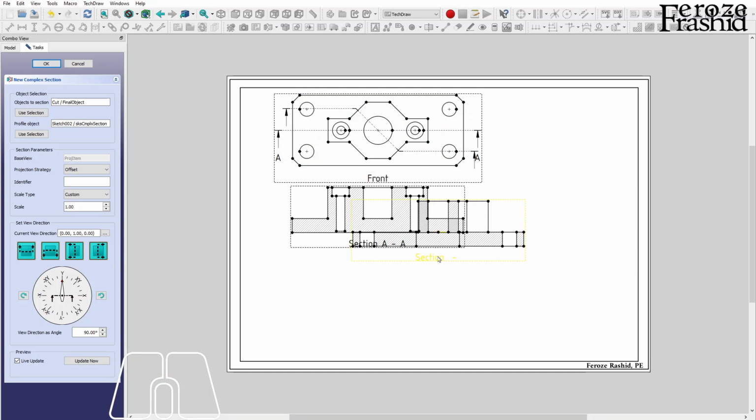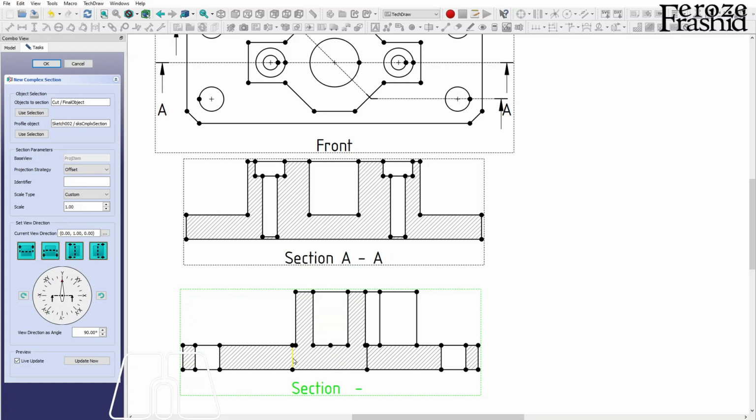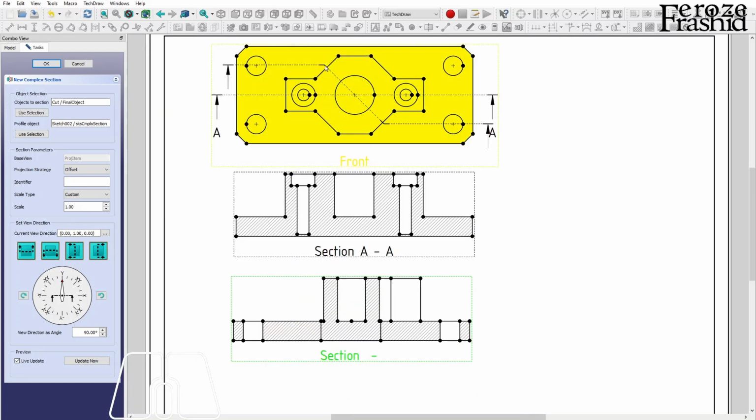Click on there. Something came up. So this is our complex section. So let's see if it matches our imagination. We come here, we cut this object, which is the hatch part. That's the solid part that we cut, and then we hit a void. That's the white space, and then we keep going through the object for so much, and then I change direction. That's this line here. It says we changed direction, and then we still keep cutting the solid object. This is here, and then the void, but the void has a base, so it's there.